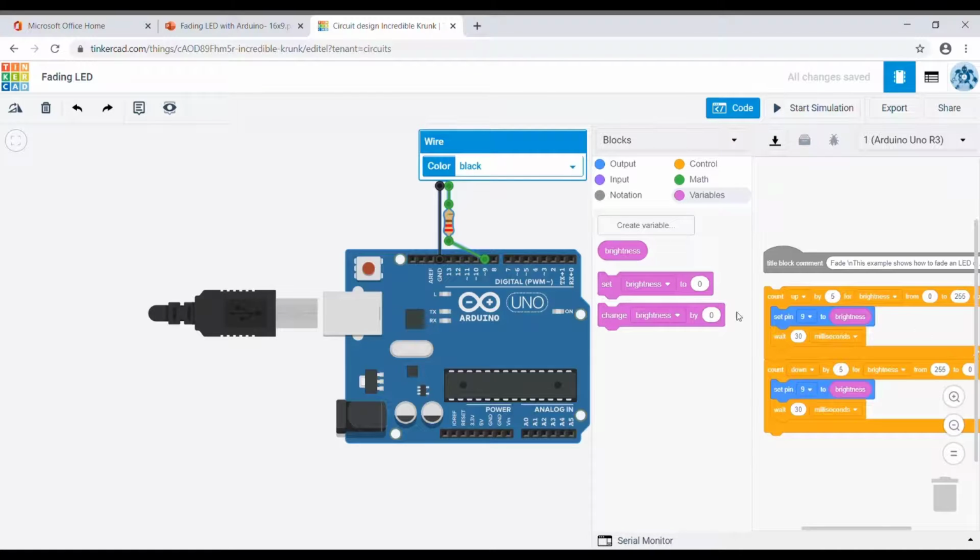But anyway, this is not 0, this is a number, so it's gradually going up a little bit in voltage. For example, suppose it is 0.2 volt, something like that. It gets more voltage and more and more. What's happening on the LED? The LED gets more power, so it's getting brighter and brighter to the end, which is 255, the maximum number, equal to 5 volt. At that moment, the LED is at maximum brightness.